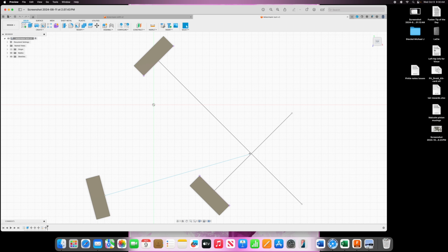So this is how I envision the control to actually work. The front wheel is just going to be a straight linear function on the stick, right? So if the stick is centered, the wheel is at 0 degrees. And if you move the stick all the way to the right, the front wheel will move to 45. So that's my limit. I'm going to range it from 0 to 45 degrees. And again, it'll just be a straight linear function based on stick position.